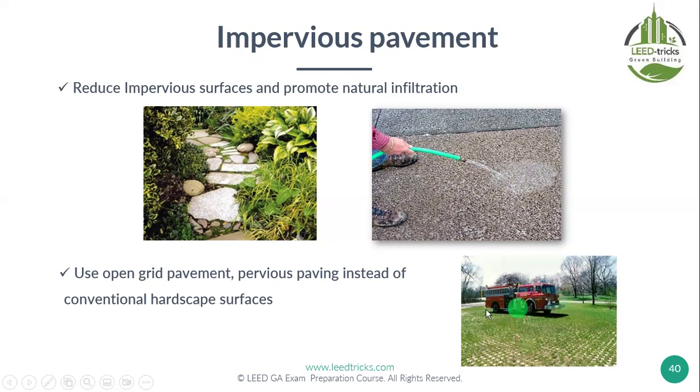Even in the park area, you can find the ambulance or fire truck standing easily and steadily on what we call pervious paving. See, the paving is open grid. It's open 50%. It's not totally closed paving. We call it open grid paving or pervious paving. Okay, remember this: open grid paving or pervious paving. See the car, how it's standing.